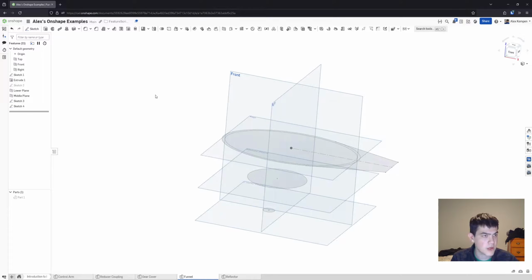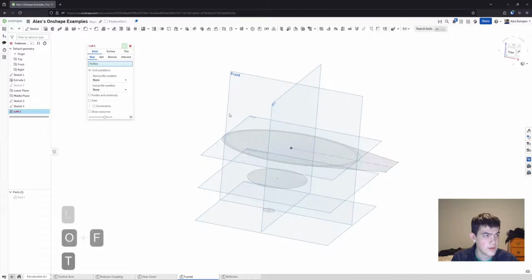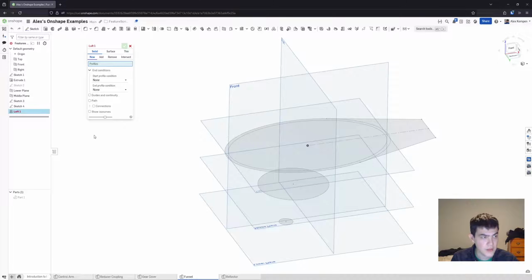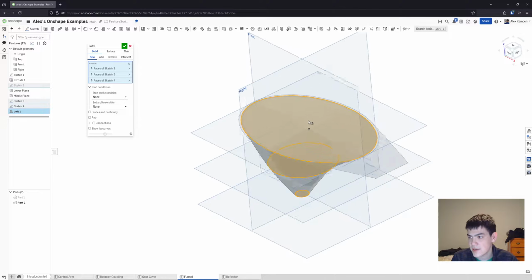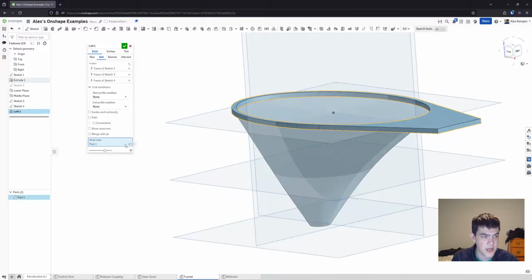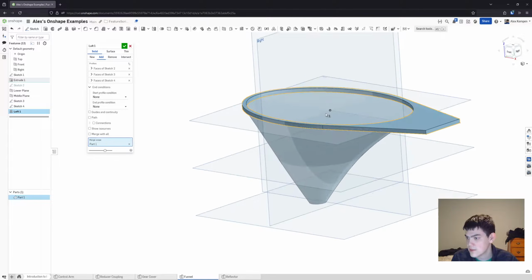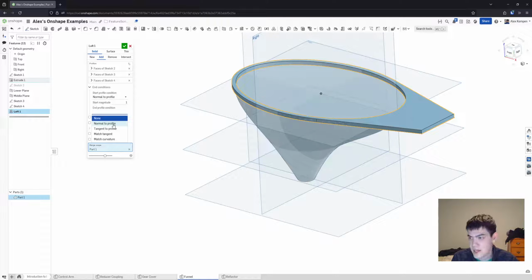Yeah, and now we can go ahead and create a loft. So I'll grab my loft tool like this. You can see it's over here. We're going to be lofting between this profile, this profile and this profile. So you can see that there. I had this part hidden, so it didn't change to add automatically, but I can just change to add, and then editing logic fills in the merge scope for me, which is nice. Everything else should be fine. This is going to start normal to profile, and it's going to end normal to profile as well, and the start magnitude is going to be 0.5.